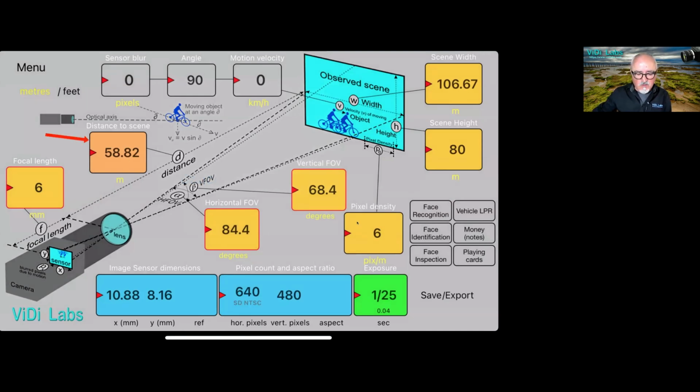As you can appreciate, now we've got a wide angle of view. That's an important part. We've got now 84 degrees horizontal angle of view. So you may say, it's the same distance, like before we had about 58.8, but you now have 84 degrees horizontal angle of view, where before you had only about 25 or something. So that means now with this sensor, with the same focal length of 6, you will have almost 90 degrees. So instead of having maybe 3 individual thermal cameras with a narrow view that can see up to 60 meters, you now can see 90 degrees almost with one camera.